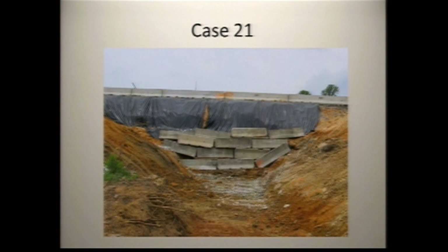You know, at first it's kind of goofy and it's not pretty, but again, just go back to the basics. Is there erosion controls? Is there sediment controls? In this case, we had a half-hearted attempt at some visqueen for erosion control, and that was it. And that obviously isn't enough to get you to the goal line.